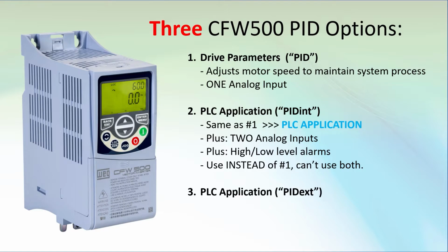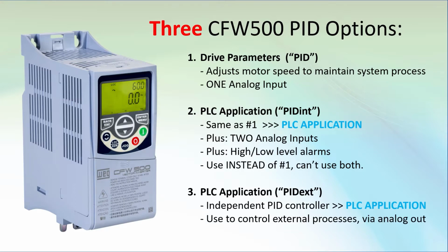The third implementation is referred to as the external PID, and it's also an application that you load into the drive's built-in PLC. Instead of controlling the drive's output to the motor, it controls an analog output, which you can then use to control some other external actuator, just like you would with any PLC or controller. So this is just a generic PLC-based PID that you can use for whatever you want. And you can use it while running the drive's built-in PID, which means you can have the drive controlling a motor and the built-in PLC controlling another process, which saves you the cost of having to buy a separate PLC to control that other process.